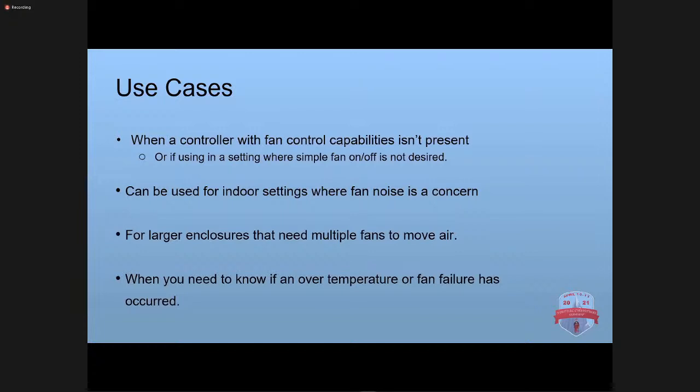But say, for example, you want it to behave differently because you've got different uses, and you're going to be operating it during the summer and the winter. You may not want that fan coming on at all at certain times of year. Natively, you'd have to go in and adjust those settings, basically increasing the temperature threshold so that it effectively doesn't come on, or disabling it entirely.